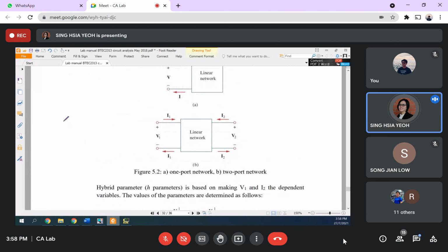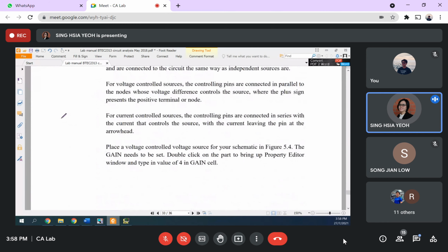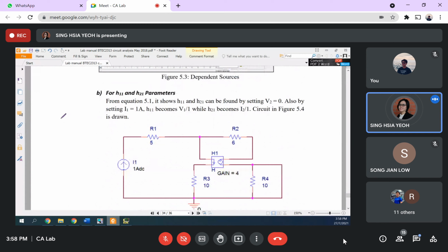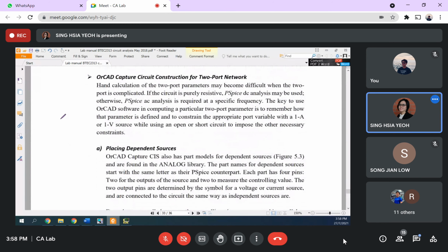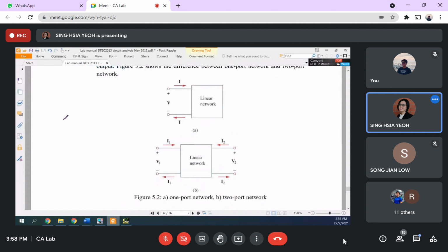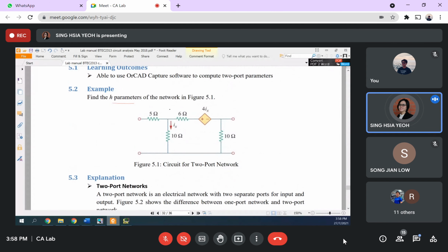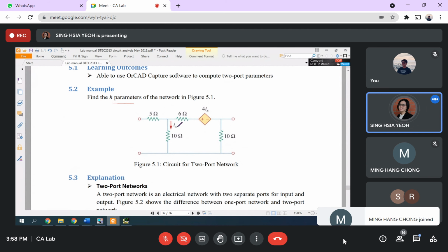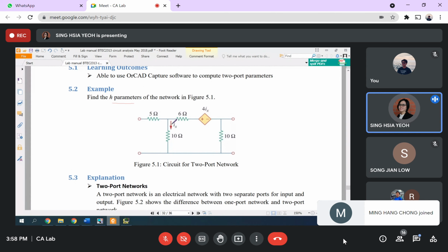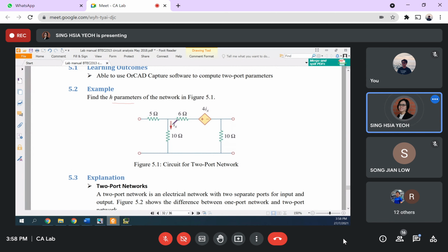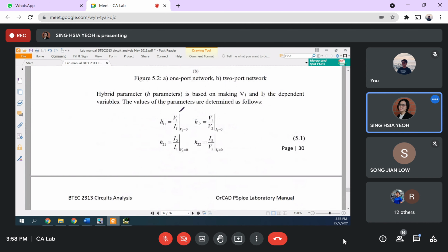And about the theoretical calculation, perhaps you would like to ask me how about it. The theoretical calculation is nothing, just a normal circuit like just now. When you short your port 2, then it's a normal circuit, and you use anything you learned before: mesh analysis, nodal analysis, all the circuit analysis methods like Ohm's law, superposition, or source transformation. With all the methods you learned before, you find V1 over I1. Maybe like current divider, voltage divider rule. Can you get what I mean?